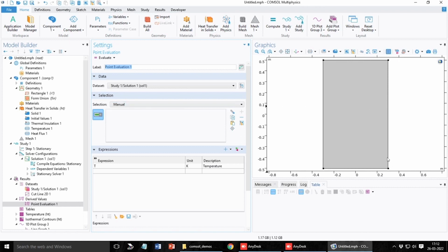But unfortunately that point cannot be selected. You can get the temperature value across the whole y, that is one option, or here you can only get the 4 corner points, whatever vertices are already defined in this problem. Or you can define a vertex at that particular point during the geometry, and then evaluate the point temperature there. That is a possibility. So, let us try to do that.